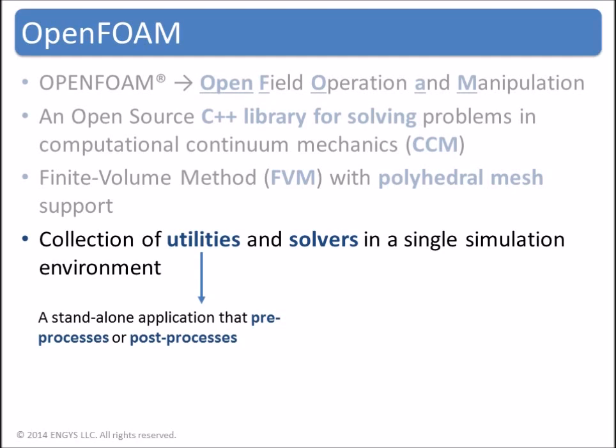This includes mesh generation or data analysis, anything that you would need to prepare a case, a case being the collection of boundary conditions and mesh and everything that you would need to begin a simulation. And a solver is a standalone application that simulates a model or models. So for instance, for incompressible isothermal turbulent flow, there's a special solver for that. If it's steady state, then we would use something called simpleFoam.